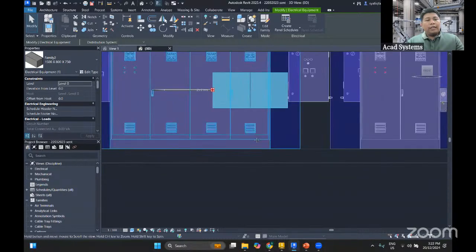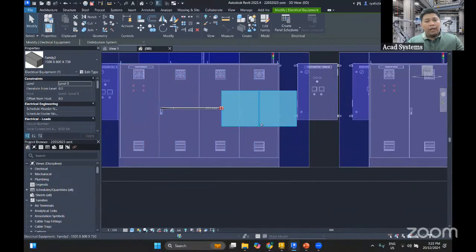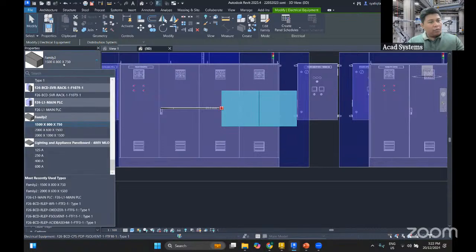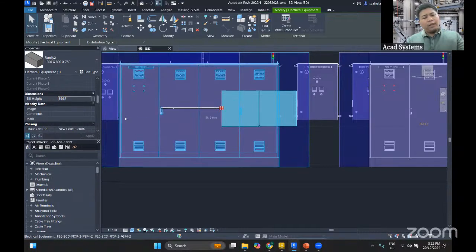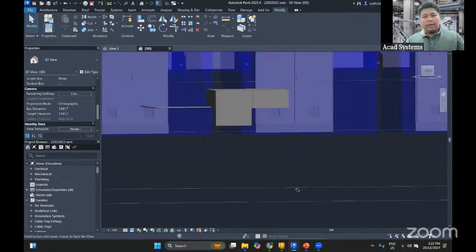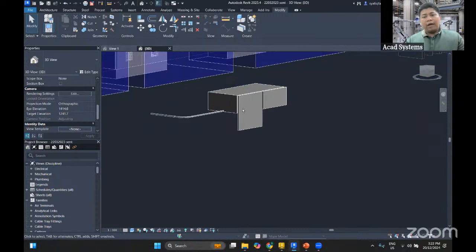For the instance parameter just now, when I click on this button, so when I go to here, you can also change this value. The sill height, you can just directly change here. For example, we want to make it a bit lower. So 500, 500. So it already dropped a little bit. Okay, so there will be some formula that is not really nice in our model. So we need to check again.